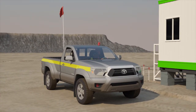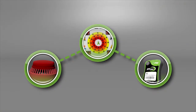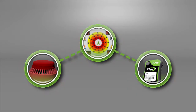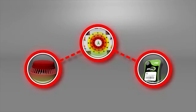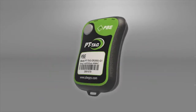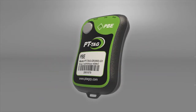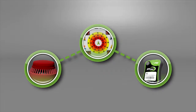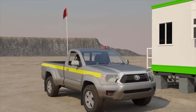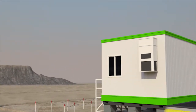To test if the PAS-Z system is working properly, turn on your vehicle's ignition. The PAS-Z unit, strobe light, and your PT tag will sound an alarm and flash continuously. This indicates that the PT tag and PAS-Z system are detecting each other. Press the button on the PT tag twice to attach yourself to the vehicle. The alarms and flashing lights will stop. You can now proceed to the vehicle testing station for a final check before entering the workplace.